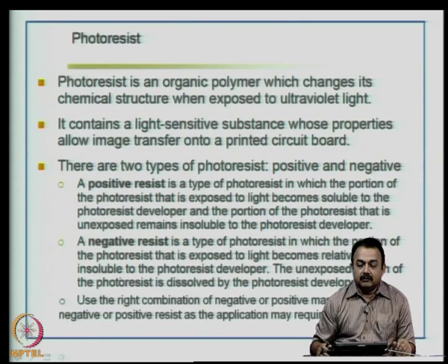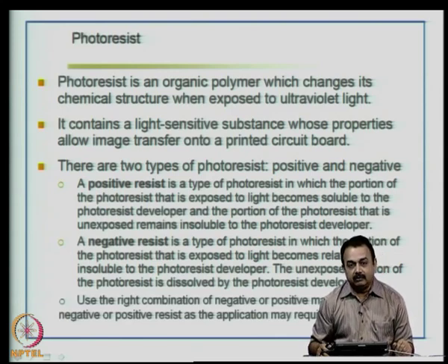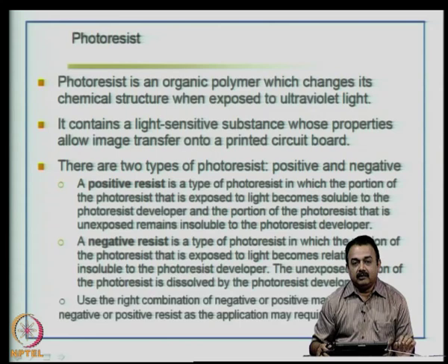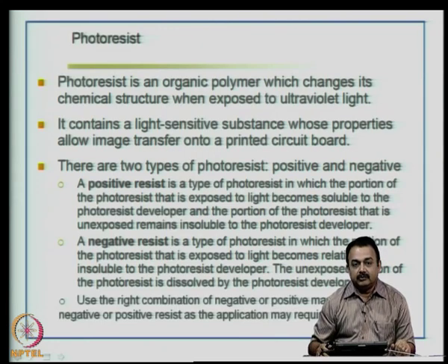Even for a 4 mil line, you require an excellent photoresist that can have repeatability, that can be applied onto this printed circuit board copper surface at very low thicknesses, so that you can have very good aspect ratio on the board. Okay? Because as a fine line demand is more in the industry, you have to do it in high volume, especially the photolithography process has to be very fast.